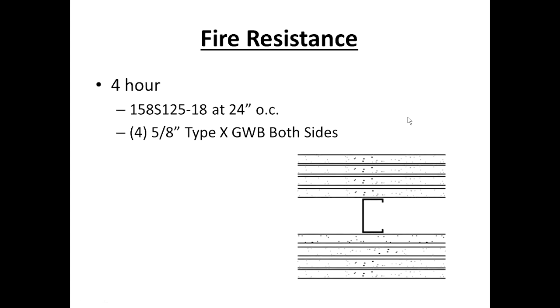To me, in all the years of testing and designing, the combination of steel for its elasticity and resilience, and gypsum panels for either its fire resistance or mass, as we'll soon learn in fire and sound, it's a marriage made in heaven, if you will. They work so well together. Think of that. You get 4 hours of separation, and that's after being hit with water for 5 minutes at 45 psi. That stud is still in place, and it's a 25 gauge or 18 mil stud.